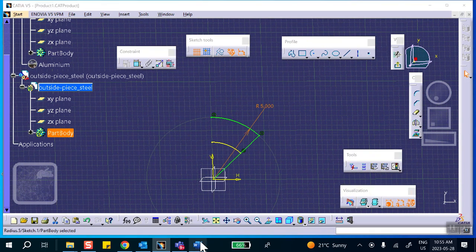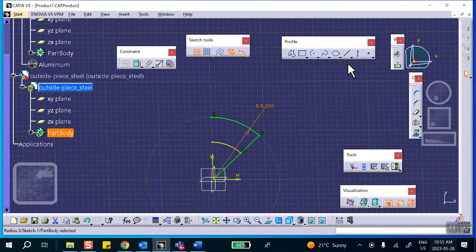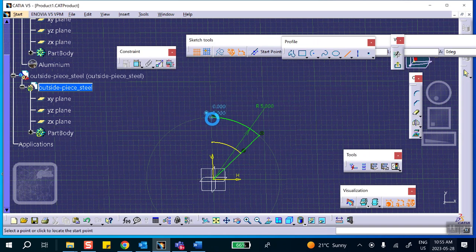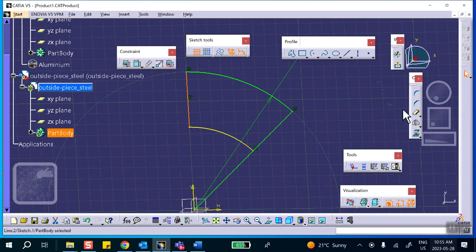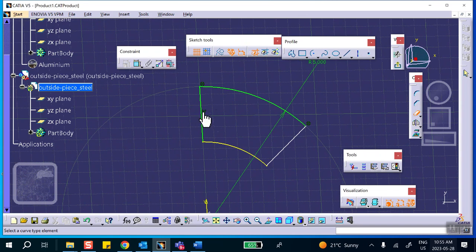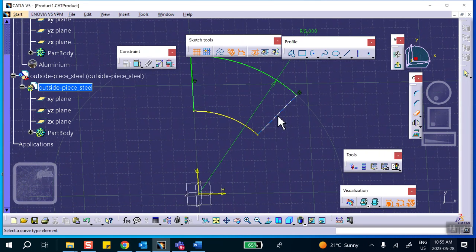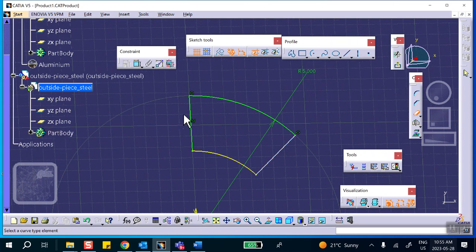And I'm doing the gray piece here. Okay, so let's complete this line from there to there. Okay. Let's do a bit of a cleanup here. I use the quick trim to get rid of this. Okay. And now, notice that because I projected, I don't have to make this angle 45 degrees because it's already 45, but that's up to you.